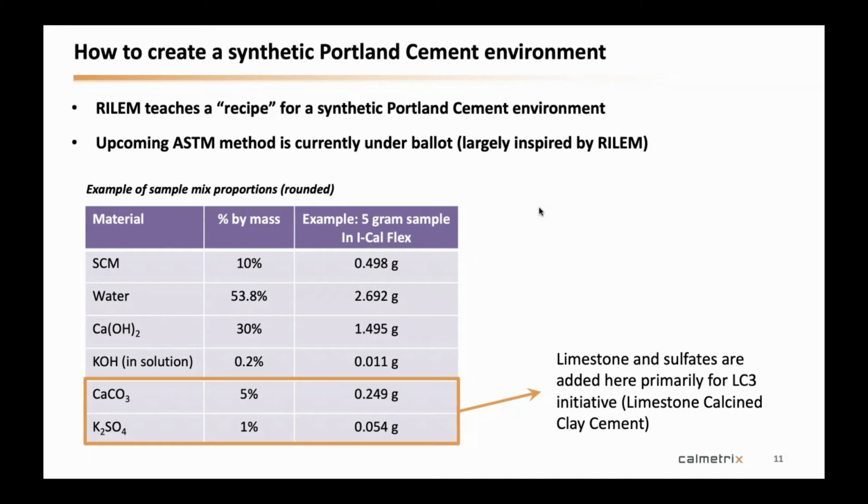You should look it up. Because this standard was initially sponsored mainly to check the reactivity of calcined clays, they also added the elements that they deem necessary to make the LC3 system work, which is the calcium carbonate and the sulfate.